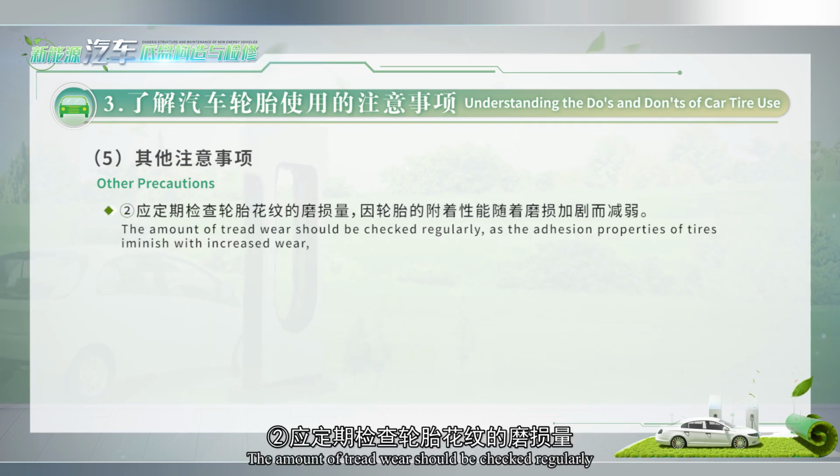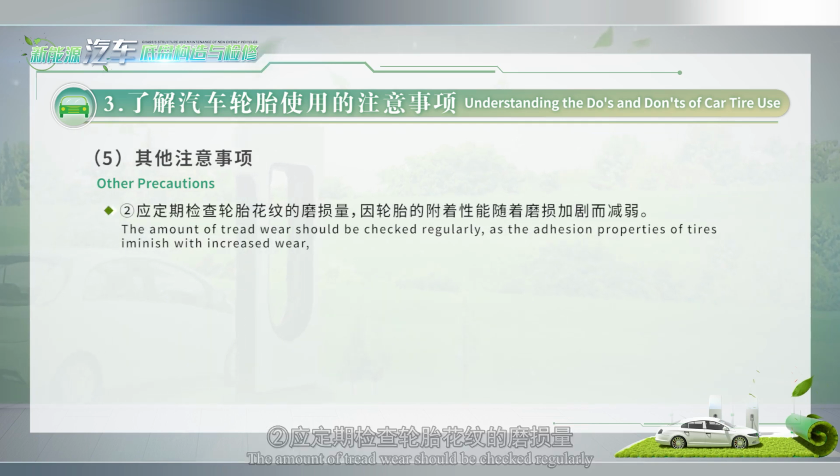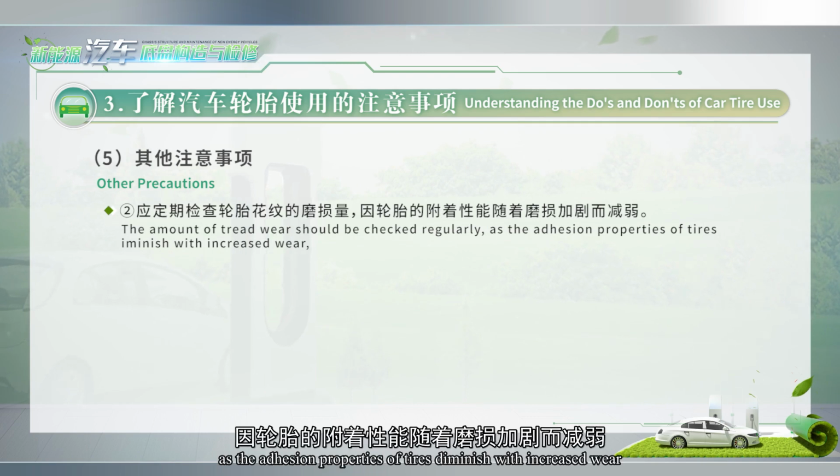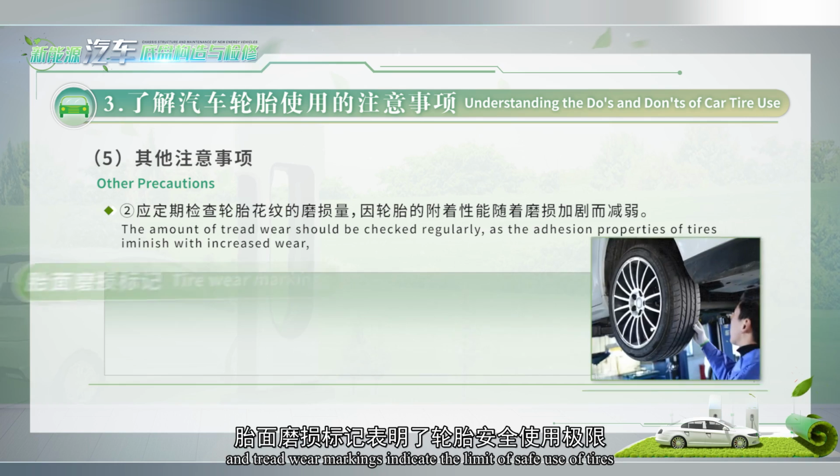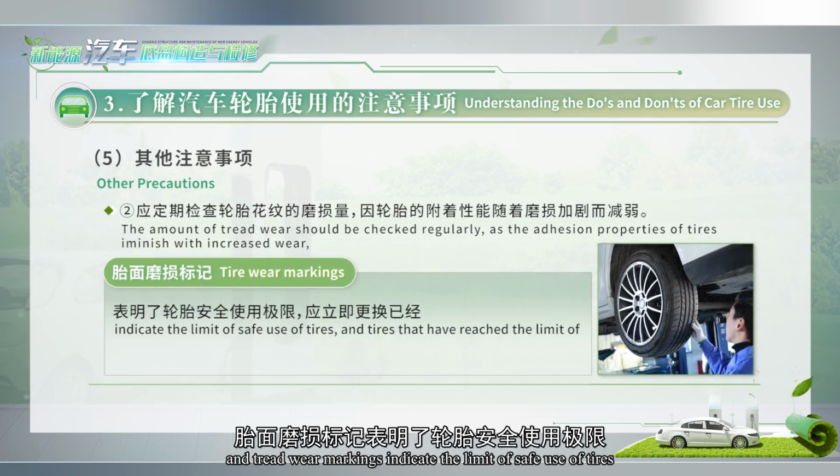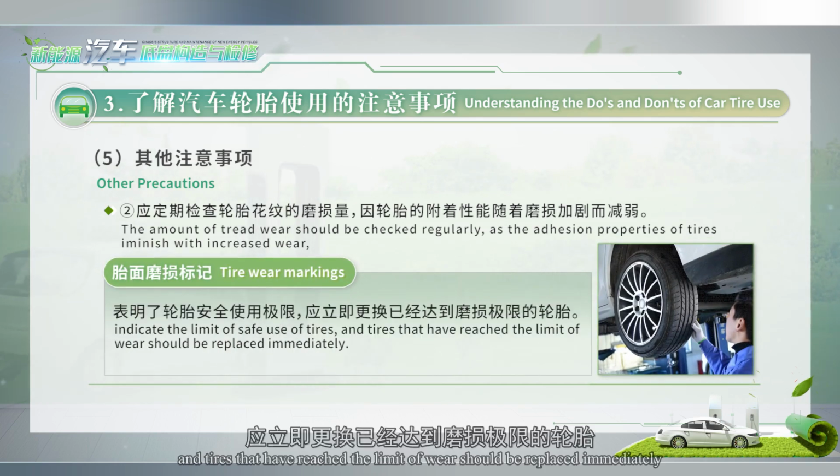The amount of tread wear should be checked regularly, as the adhesion properties of tires diminish with increased wear, and tread wear markings indicate the limit of safe use of tires. And tires that have reached the limit of wear should be replaced immediately.